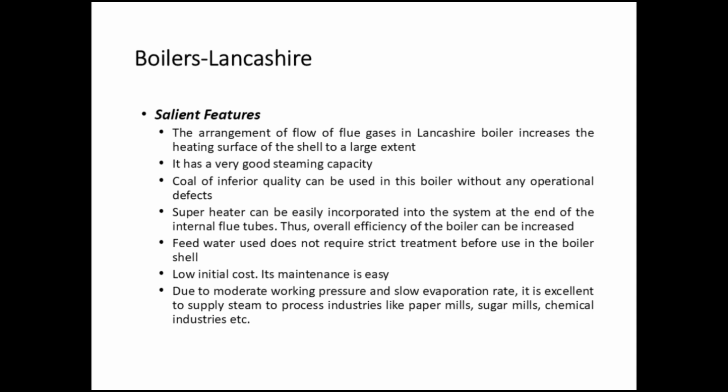Coal of inferior quality can be used in this boiler without any operational defects. Superheater can be easily incorporated into the system at the end of the internal flue tubes. Thus, overall efficiency of the boiler can be increased. Feed water used does not require strict treatment before use in the boiler shell. Low initial cost. Its maintenance is easy.